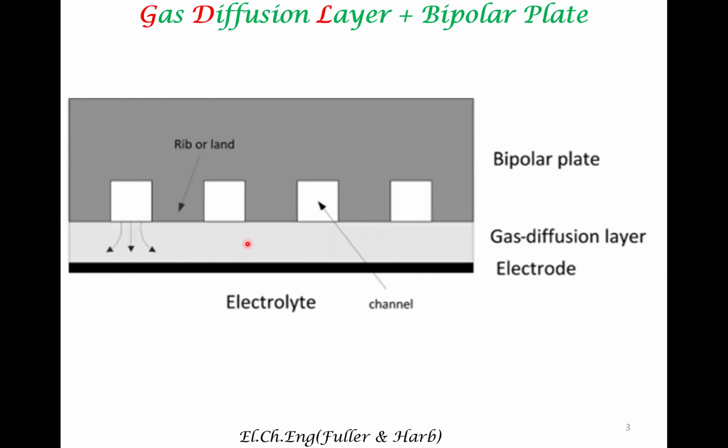So the gas diffusion layer is often very thin, maybe about 200 micron thick. It is porous. It is also an electronic conductor, and it allows for the passage of these gases too. So you should relate the gas diffusion layer to concepts which we have covered in the past, especially on the three-phase boundary in a porous electrode. Please look at the previous lecture on this topic.